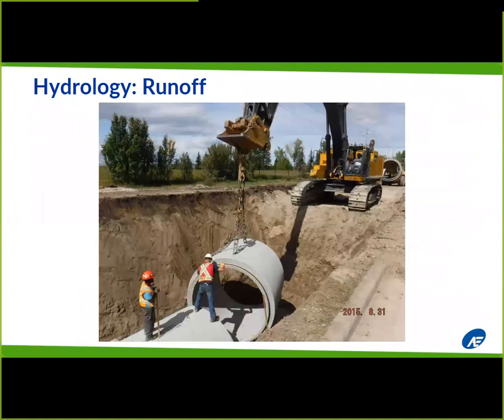And once we've got all of that, then we end up using some more software to combine all of these little hydrographs from every catch basin. And that's combined to estimate the required pipe sizes. So I've got a picture here from a project that, it's really just trying to show you that the end result of all this work is trying to size physical infrastructure that we can build to protect communities from these design events.